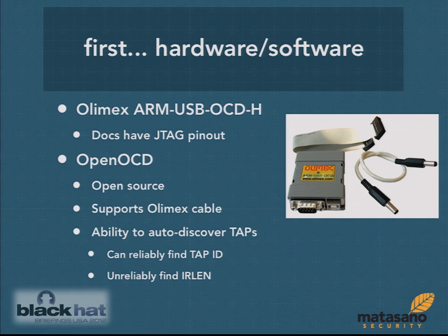And reading through the documentation, two key points stood out. One was that it can reliably determine the tap ID, but unreliably determine the IR len, which is instruction register length, which I'll talk about later.